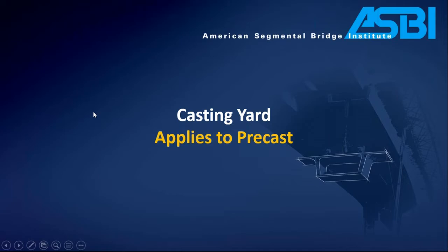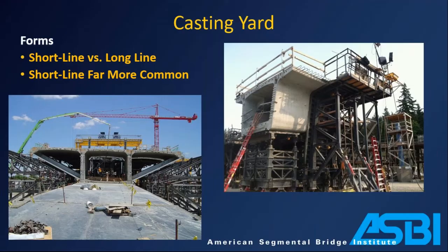So next topic, casting yard. This is for precast only. Obviously, you don't have a casting yard for cast in place. You'll hear two different phrases when it comes to casting yards, long line and short line. Long line is not that common, but just mention it here. Short line, majority of the segments that are built these days are short line.